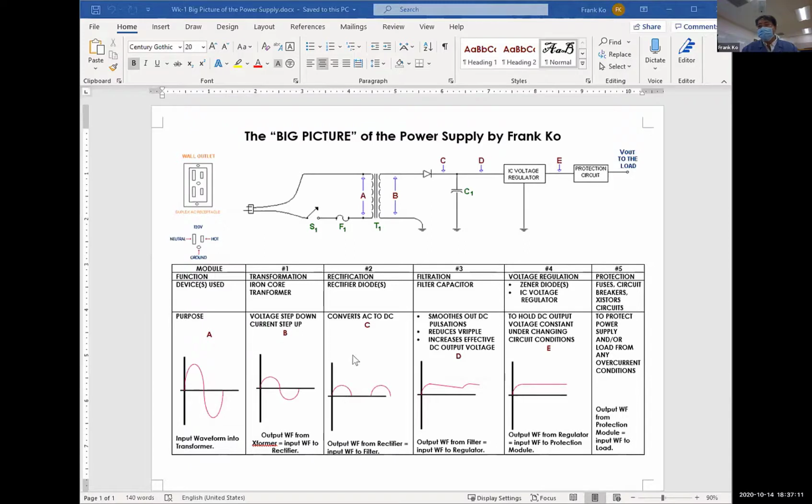If you take a look at waveform C, ripple voltage is the difference of voltage between the positive peak and the 0 line. That entire bump, that entire peak is ripple, whatever that works out to be. If it's a 40 volt peak, then it's 40 volt ripple, okay? So ripple voltage for these waveforms is defined as from the top of the peak to the bottom of the valley, if you will, of the waveform.